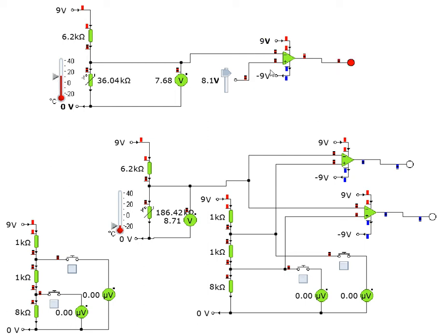Now, I was switching this op-amp at 8.1 volts. I'm using a variable voltage supply to do that, but I could have used a voltage divider. Here I've got a voltage divider, that one there, I'm getting out 8.1 volts. I've got another one here, and I'm generating 7.2 volts. Here's a voltage divider again, so that'll be 8.1 volts, and there is 7.2 volts.